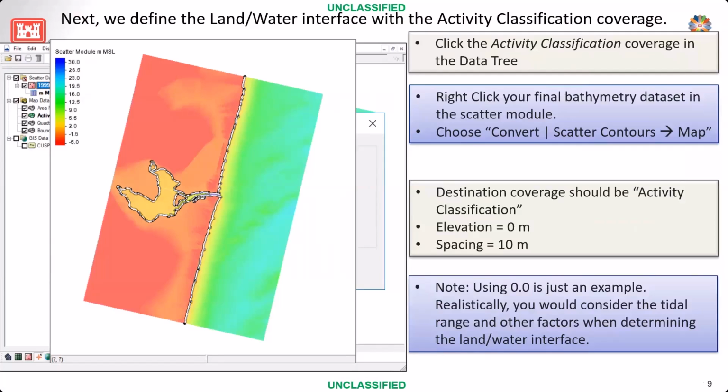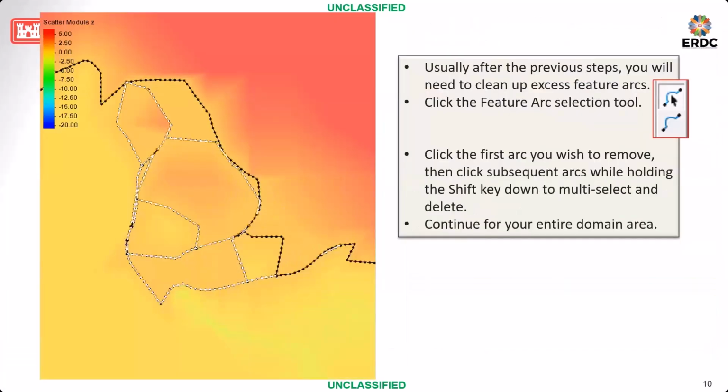Now, when we do this, we can do this a couple of times. So for example, maybe you want to add another little polyline that goes, excuse me, got to point with my pointer, further around, or maybe you create a few different contours and then splice them together to be your active boundary area. So now that we've exported or converted those into the map, we now need to make a single line that will be easy to form the bounds of a polygon that we can then click and set as active or inactive. So we often have to clean up this polyline.